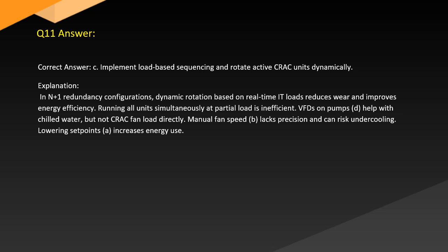Answer. Correct answer: C. Implement load-based sequencing and rotate active CRAC units dynamically. Explanation. In N+1 redundancy configurations, dynamic rotation based on real-time load reduces wear and improves energy efficiency.